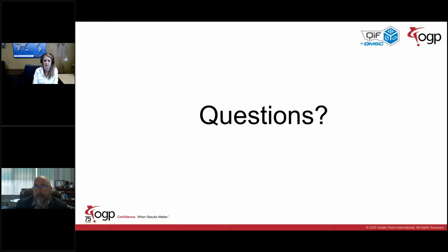All right, very well. Next question, is there a preferred neutral CAD format? Is the design module able to update the native CAD file as well? Yes, so the preferred neutral CAD format for us is QIF. Obviously, well, not obviously, but there's STEP AP242 as well. But QIF allows you, like Tom explained, to associate that additional information that can be used in metrology and manufacturing. It has that really flexible framework that allows these derivative models and derivative products to work with it. And like I did show it in the demo.